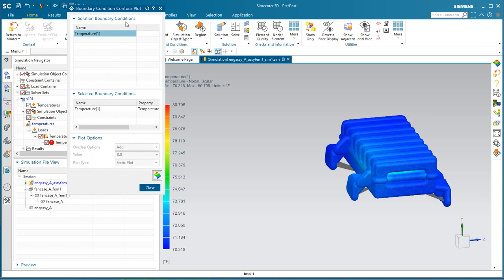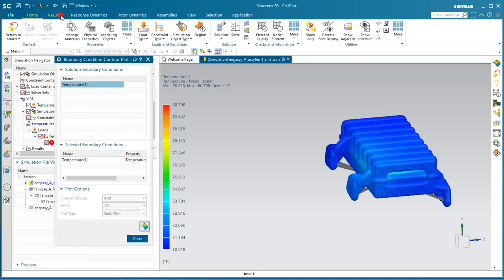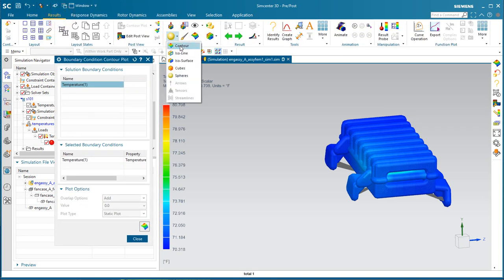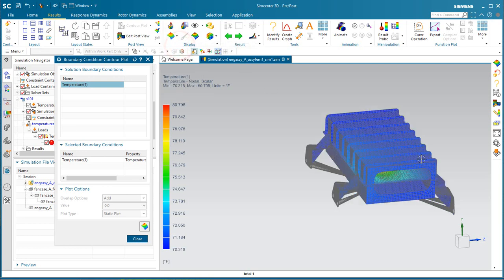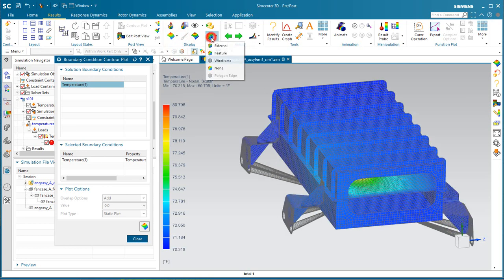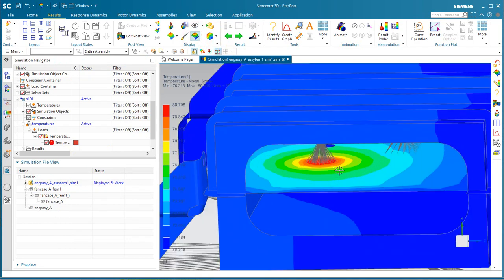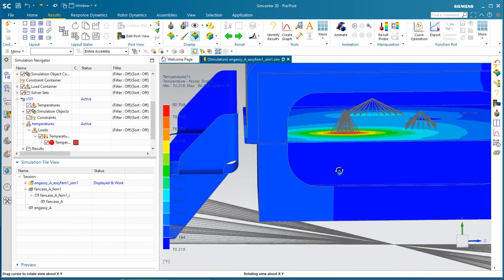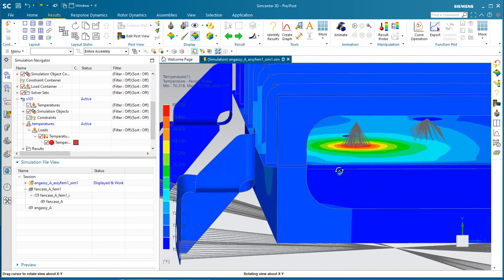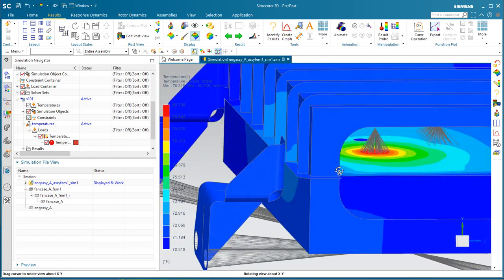Now we can plot to see how those temperatures will be mapped based on our interpolation algorithm that we had selected with Delaunay Fast. So here you can see the temperatures mapped onto our mesh, and that looks right. We've got some dissipation from the various board components, you can see heating up the model.